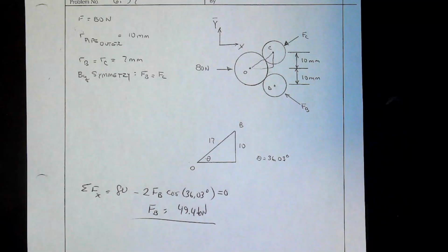At the other end of FAC, we have the pin where everything came together. We'll just bring that down real quick. The force going down here means that this is pushing back up, equal and opposite, so we have a force coming up into that. Now I will comment, since you know this pushes down and we have the equal and opposite coming up, that alone means that FAB must be pointing down. Because if this goes up, this is horizontal, that's got to go down to balance it.